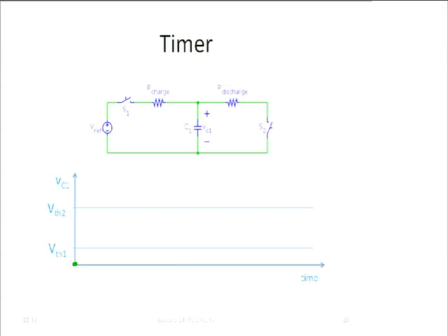Yeah, it charges up, and it goes up to what voltage ultimately? If we wait for a very long time, Vref, right? Because we are really then, this is a short circuit here. We are charging the capacitor through our charge and from Vref. So ultimately, it's going to reach a value Vref. Of course, it would take infinite amount of time.